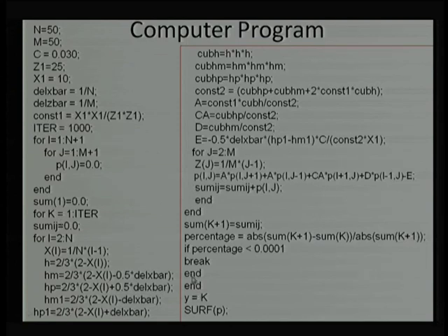So, this ends the program, this very simple program. Finally, whatever pressure we calculated here, we can plot as a command surf, which is 2-dimensional, or obviously gives a 3-dimensional profile, with x and z, and p as the height of pressure. We can also find out how many iterations really happened in this whole loop, maybe 30, maybe 23, maybe 53. It will come out, and it will show whether the solution is right.